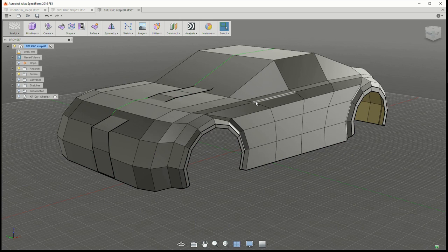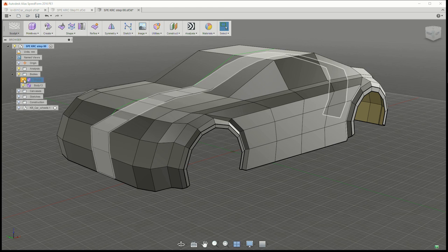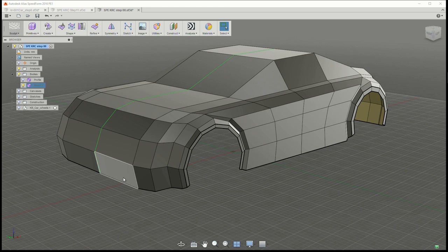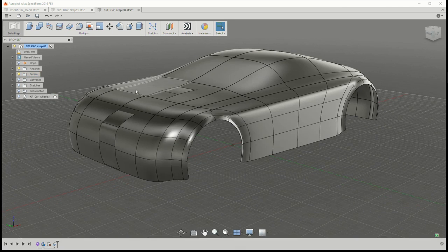All right, so a mode that I haven't shown yet is this box mode, and this would be the actual patches themselves. So if there was a way to export this, this is exactly what you're looking for. Yep. So it's there in the code. It's just not exposed to export out. The other thing that you should know about is when I go into detailing mode, and I totally didn't talk about this, this is now a B-rep representation of it rather than a T-spline representation. So these modes are coexisting with each other.